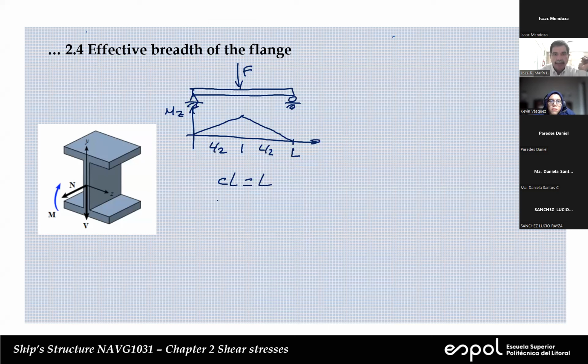Okay. Now, remember, this is the distance between the points of support, not the total length of the beam. You have to be careful because the beam was a little bit longer than that. But we need only from here to here. That's all what we need. Now, about here, more or less, let's call it X1. That's the position where you have the strain gauges.